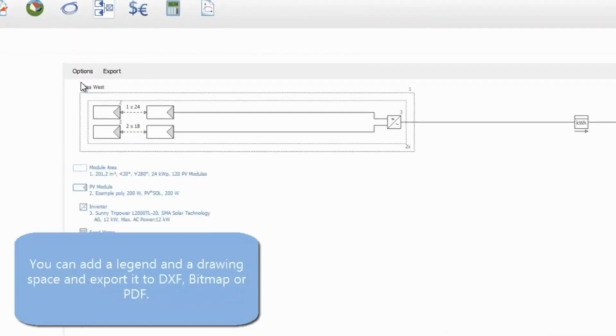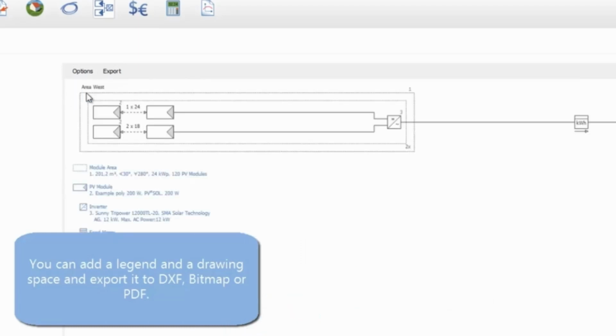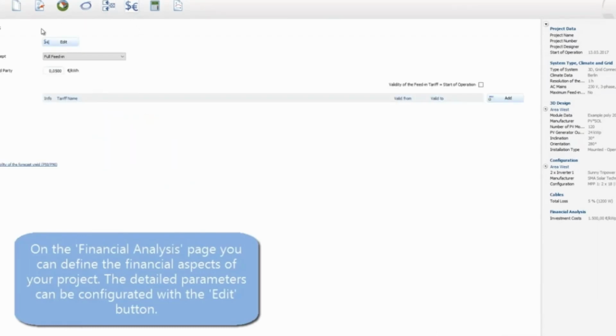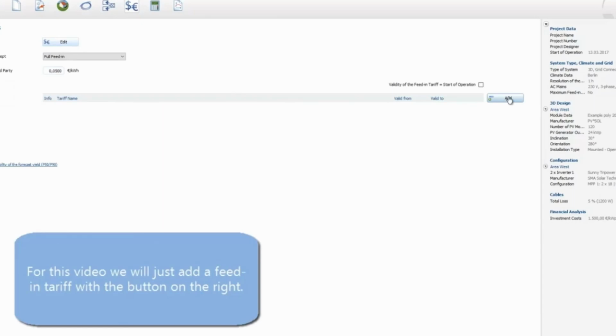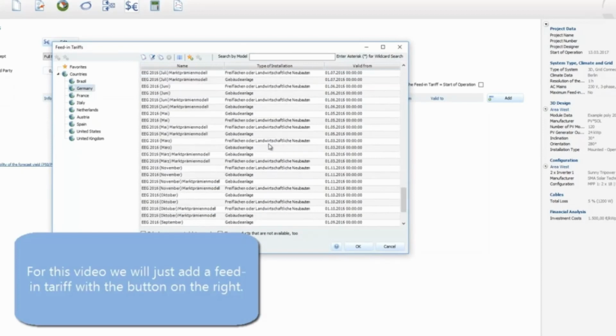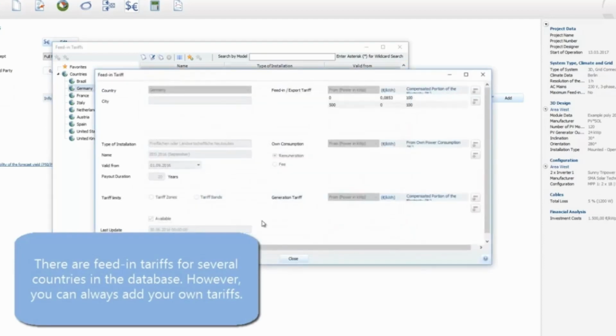In the configuration, there are two strings attached to one inverter. Depending on the type of inverter, whether it's a pure string inverter, which really has one string, or you have also several ones. Also the number of modules, as we calculated already, depends on the maximum system voltage and the maximum power output of the inverter. From the input side, it's important that you fit to the range where the maximum power point tracker can act under all conditions, so for cold conditions and hot conditions and different irradiance conditions also.